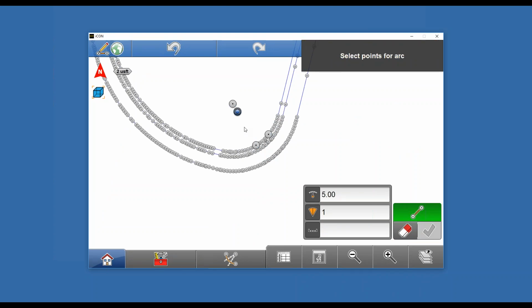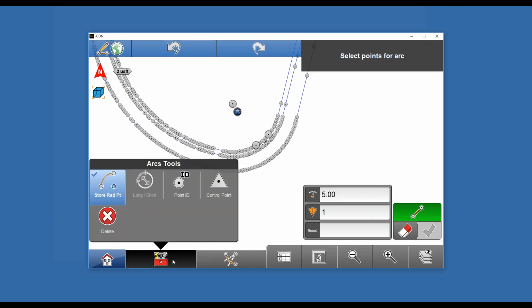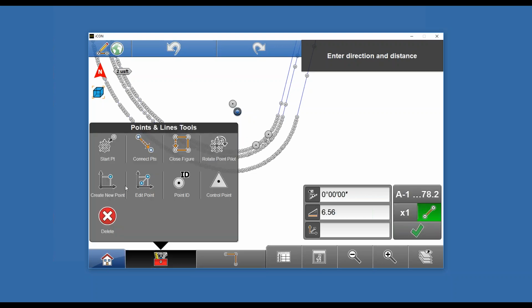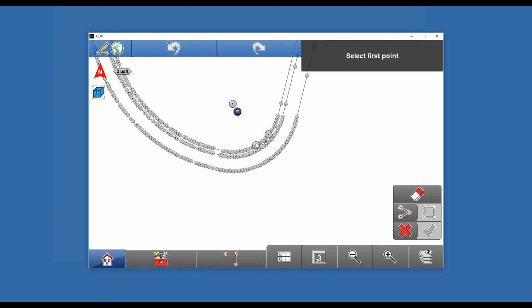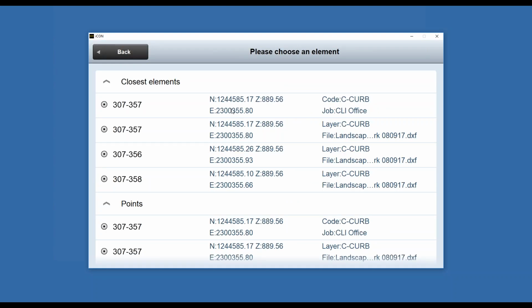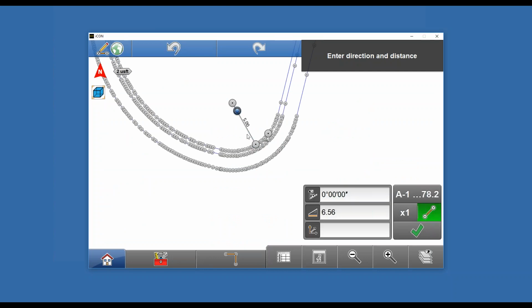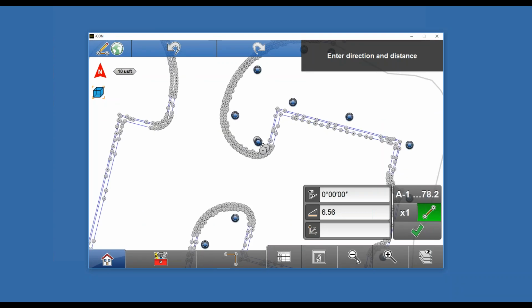If I want to be able to see that it's a 5-foot radius on the screen, I can go in and go back to my lines feature and just do connect points. Select any point on the arc and my radius point, and it'll draw the dimension on the screen for you, so you see that that is a 5-foot radius, and give you a line to show you which radius this is applying to, so it'll give you a direction to it. Ton of other features in here.